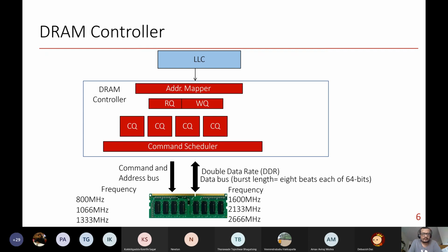That means that particular row, wherever it is present, will come into the row buffer, right? So the DRAM controller populates these commands, and there is a scheduler similar to any other scheduler that you must have studied in your undergrad or graduate level courses. The goal of this scheduler is to optimize, let's say, latency, fairness, and so on.